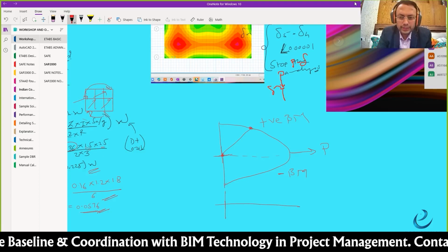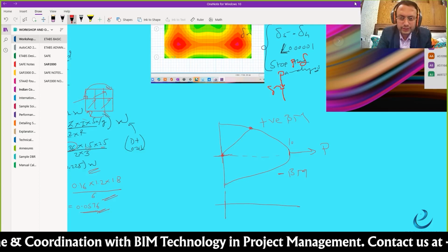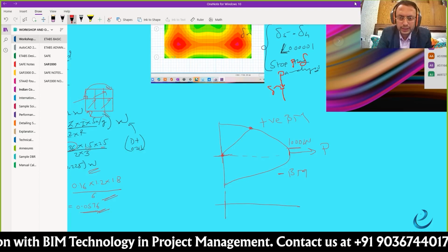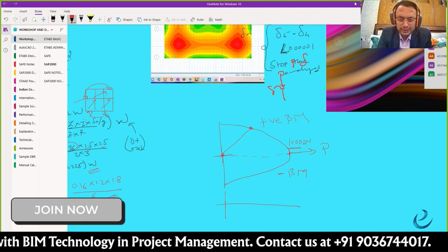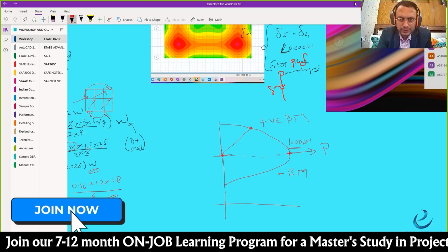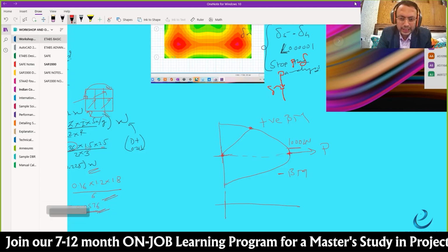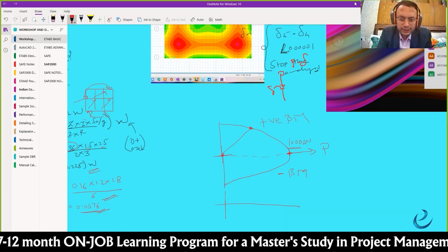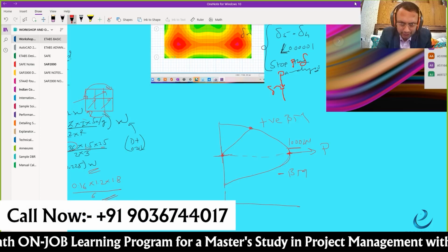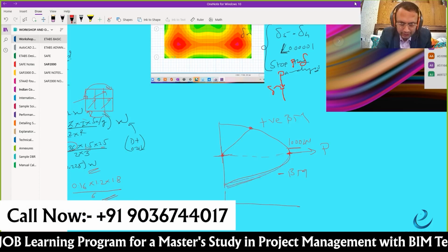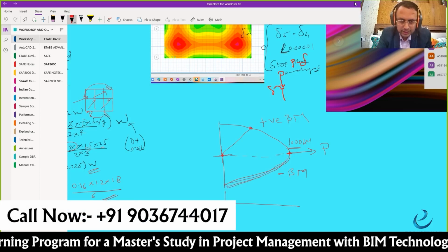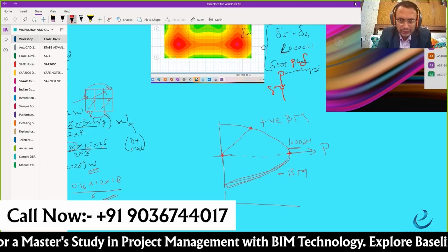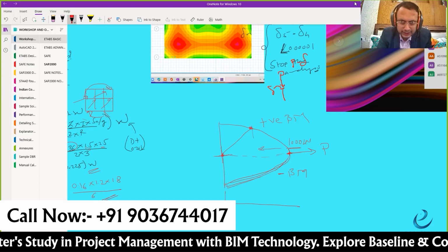It means, let's take some figures. If 100 kilonewton or 1000 kilonewton is the capacity in P, since it is on this axis, the bending moment will be 0 only. Any other bending moment, it can't take. But if you see this particular point, the value is increasing. The moment the negative or positive bending moment value increases, the P capacity gets reduced.